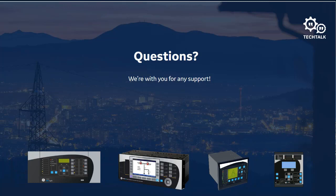For example, if we swap the phases, so we wire B phase to A, C phase to B, and A phase to A on the input of the relay, our negative sequence quantities would be 100% and our positive sequence quantities would be 0. So if we see that, we know we've got a wiring error.